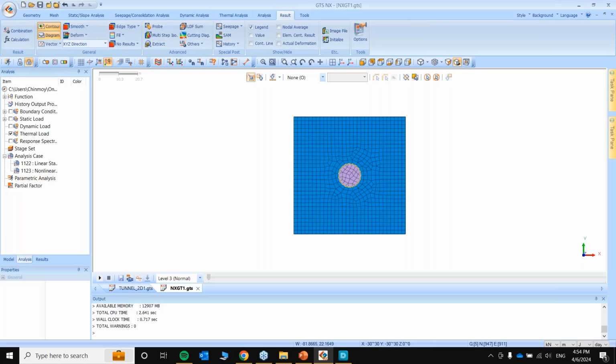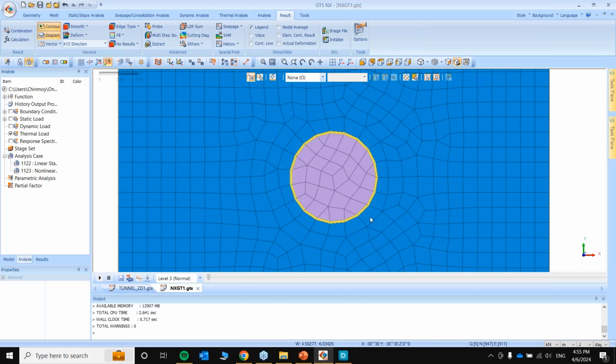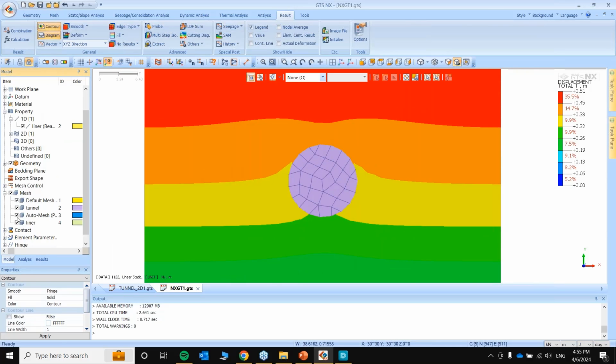So I had one more question that the soil layer in the face and around TBM circumference are a bit disturbed. Yes, they will be. So how can we apply disturbed properties? Any correction needed in properties? So in those cases, there are multiple ways to model that. Either you can model those particular zones as weak zones, because they will be weak zones, right? The stiffness only increases some distance away from the excavation, not exactly at the periphery. So let's say in this particular model, this is my weak zone. So what I can do is I'll reduce the soil stiffness properties and assign a new property in there. Just allow me a moment. After checking the result of this particular model, I'll show you how to do that.